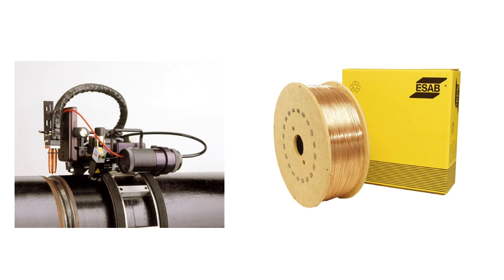This is another welding process which is known as MIG welding. The setup which is shown here is an automated welding known as orbital welding, which we use for welding pipelines. Nevertheless, it is metal inert gas welding or gas metal arc welding. Here too we use a spool of electrode wire which is fed into the weld and melts with the arc which is produced and gets added on to the weld produced. It is basically a consumable electrode.